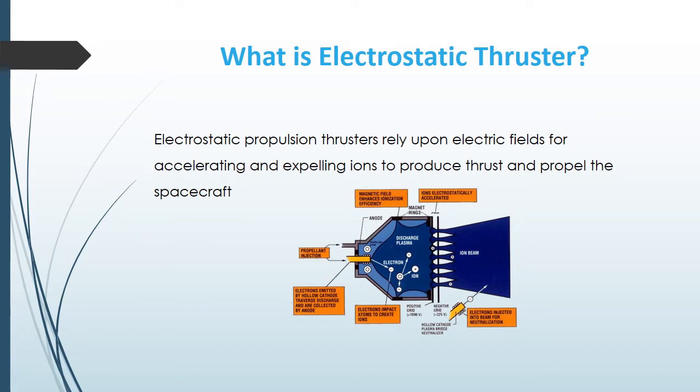Electrostatic thrusters provide relatively large Isp values, ranging from 1000 to approximately 10,000, and also have relatively high efficiency, ranging between 55% to 98%, while electrostatic thrusters produce minimal thrust relative to alternative propulsion methods. The various implementations of this technology provide advantages not offered by other propulsion methods.